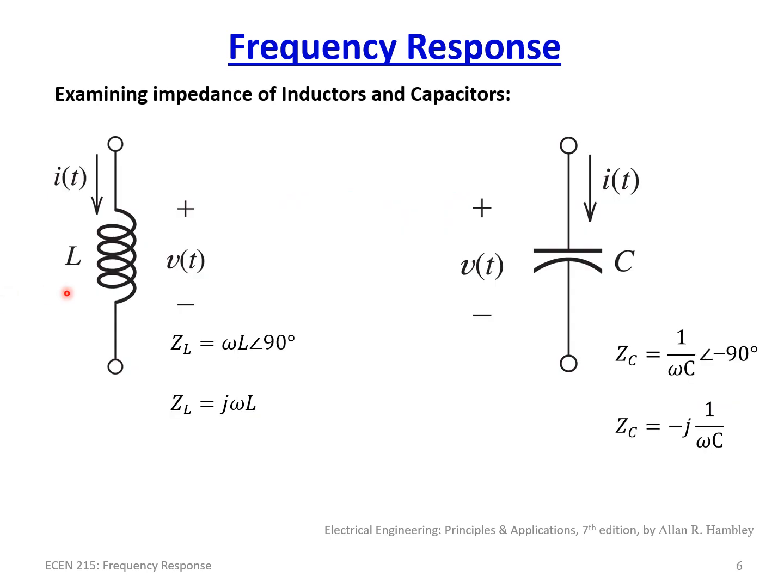So what is frequency analysis? Well, so far in our circuit analysis, we've been looking at inductors and capacitors. Of course, the impedance of a resistor is the resistance, so there really is no frequency component of an ideal resistor. But obviously with an inductor there is: the impedance is jωL, and with the capacitor, Z_C is 1 over jωC, or minus j over ωC. Now the key thing to realize here is this concept that we truly do have a frequency component.